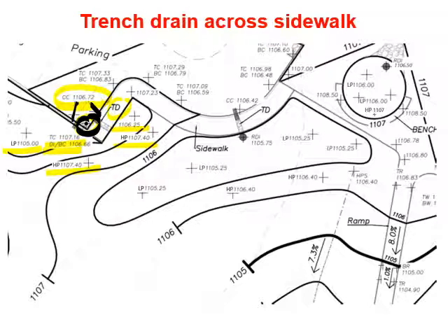The elevation for the drop inlet will always be the same as the elevation for the bottom of the curb. This is not true for raised drop inlets, but it is true for the drop inlets.